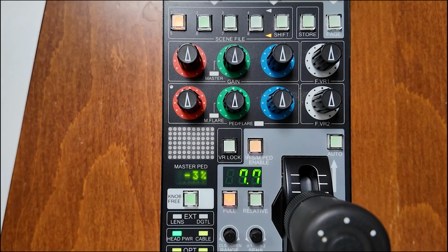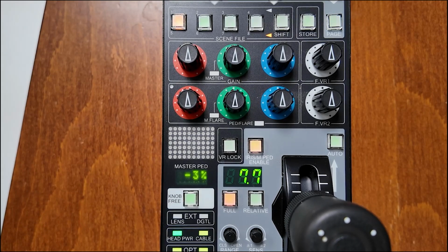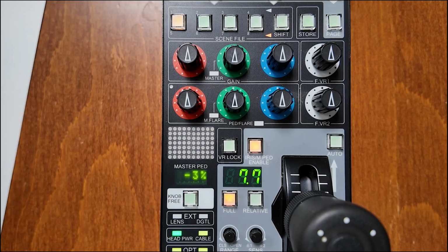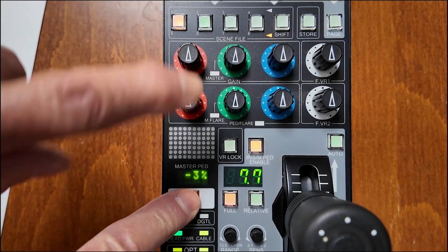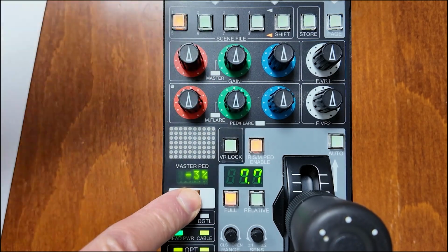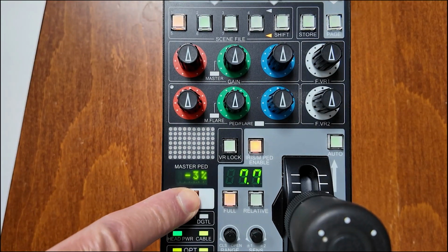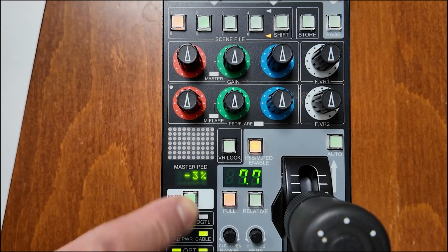But if I did, for example, a black balance and I did not center my potentiometers, by mistake I guess, and we come back and we see that they're pointed at arbitrary directions, and yet the camera is black balanced, and I would prefer that the black levels were at 12 o'clock, having achieved a proper black balance, then I would push and hold knob free and turn the appropriate VR. While doing so, no change occurs to the camera. So we're just repositioning the potentiometers.